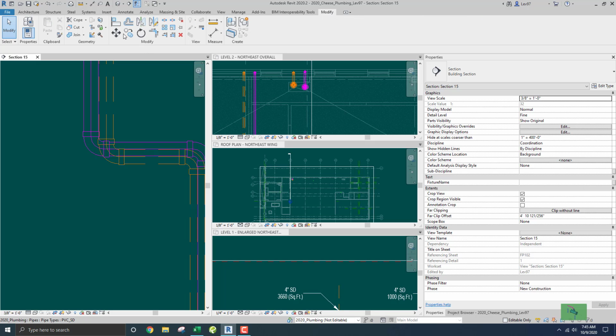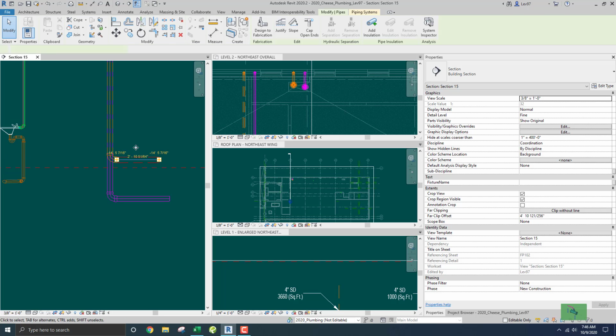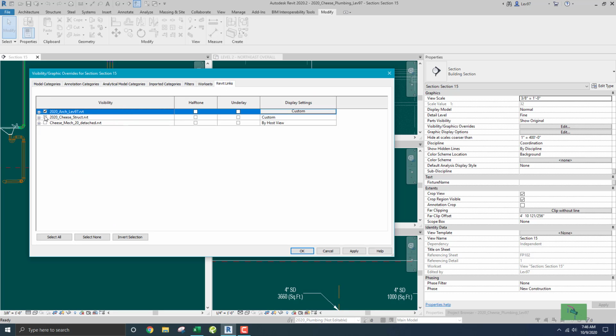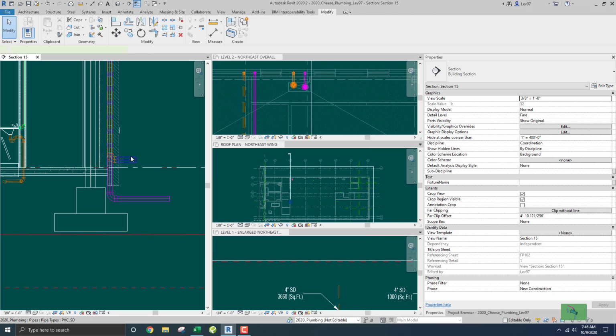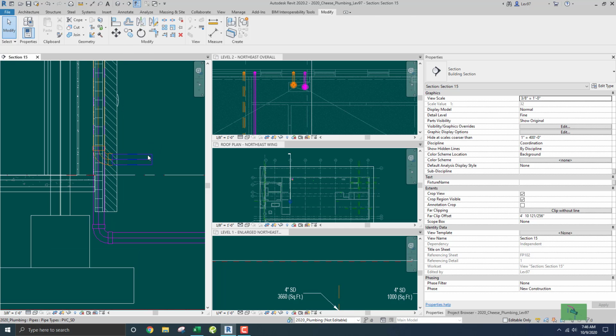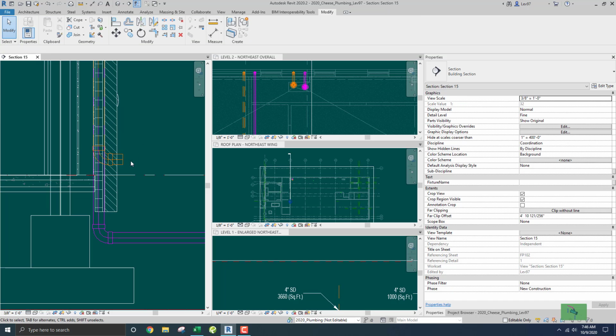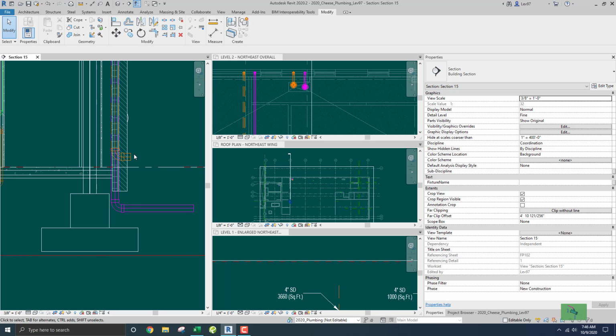So I'm going to line up these guys so that they are a little bit parallel to each other. Okay, that's 1 and 1, 2, and here this overflow is going to be a little bit higher. Okay, I think I can do this and just draw it back just a little bit. Turn on my models, in particular my architecture model, because that's the wall, and I don't want it to be too far out because it's an overflow drain that's going to spill into. You can either splash it down onto the ground, or you can use a scupper, which is more or less a kind of a diverter kind of thing. So it kind of fits on the wall, blah blah blah kind of thing.